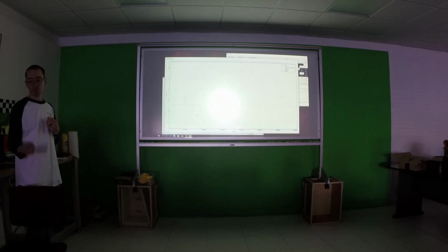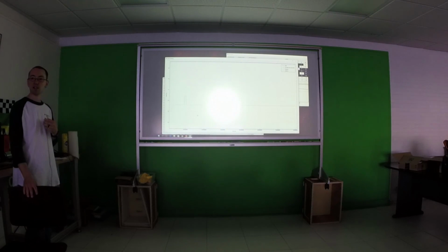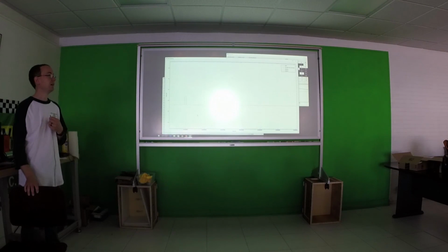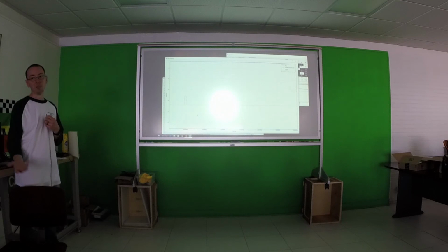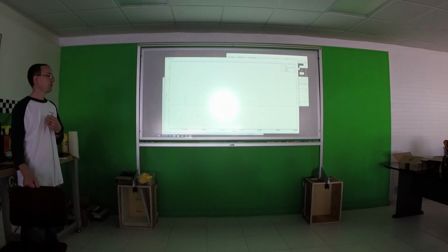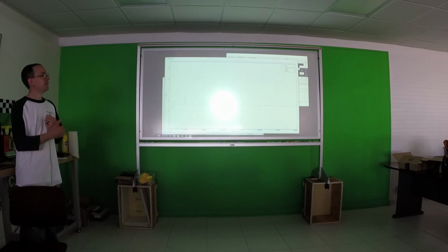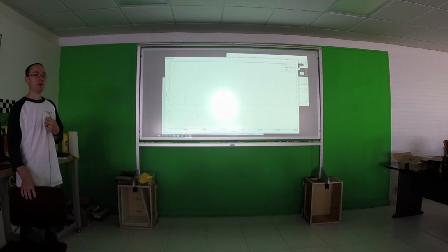So you're going to get devices on the network that have a filter for 3 messages, let's say. That's the only messages they listen to. So that's probably why the duplication is there. They're all listening for different messages and filtering out everything they don't care about. When we get on and listen to everything, the data rate gets pretty high. Yeah, the drive bus is about 1,800 frames per second. So it's more than 1 frame every millisecond.